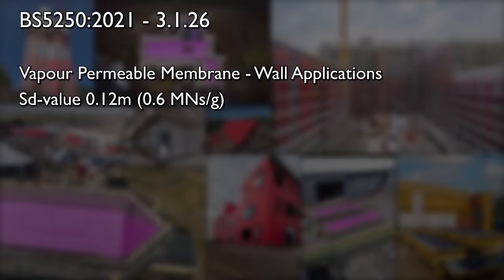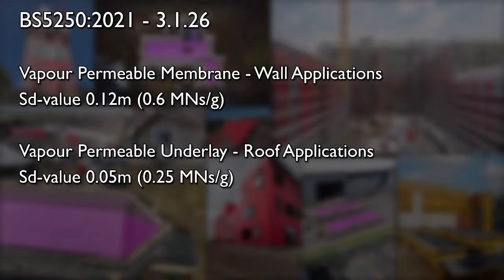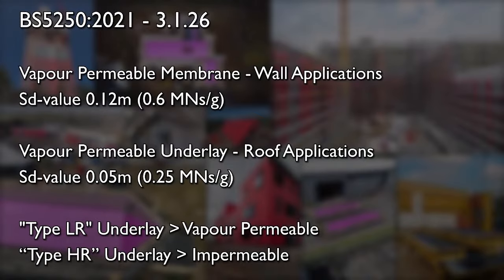In a wall, the vapour resistance must be less than an SD value of 0.12 metres, or 0.6 meganewton seconds per gram. In a roof, this requirement is lower at 0.05 metres, or 0.25 meganewton seconds per gram. Vapour permeable membranes for roof applications are also termed Type LR, or low resistance underlays. This is to differentiate them from high resistance underlays, which are non-permeable membranes like traditional bitumen roofing felt.